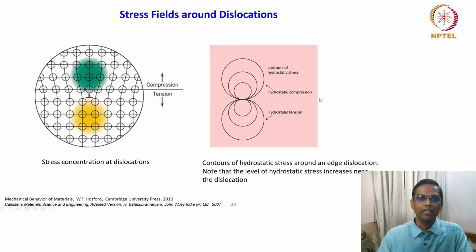Okay, let us continue our discussion on dislocations. In the last class, we looked at the detailed geometry of dislocations and types of dislocations, and we also looked at the energy of dislocations. In this lecture, we will see stress fields around the dislocations.